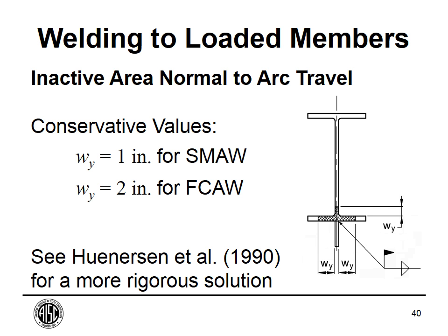In other words, if you're welding along the entire length of the beam, you're going to have a maximum moment within that beam that is there at the time of welding. So you would take this chunk out at the point of maximum moment. Or, I've never had this controlled, but the maximum shear could also control too. So you may have to check two sections, if that W sub Y takes out a little bit of the web for the shear strength too.